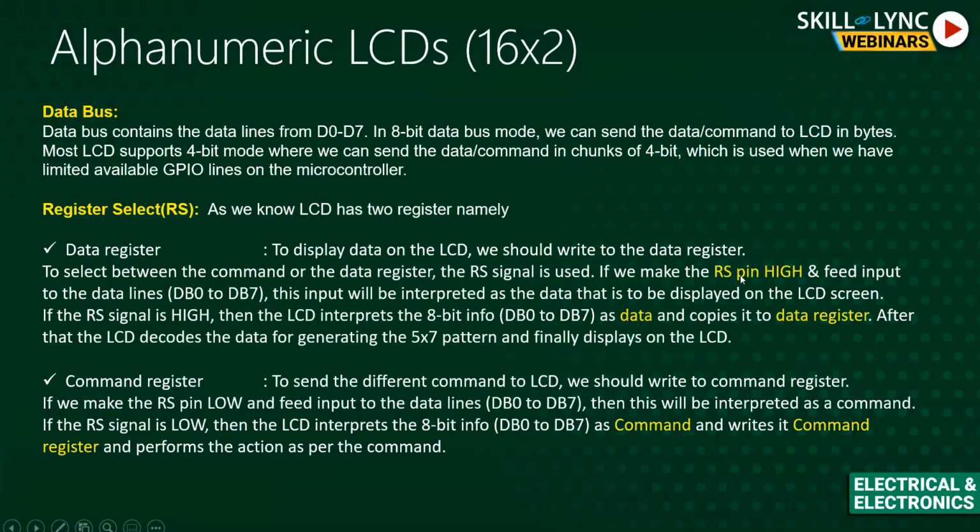Now after configuring the RS pin to high, whatever value I load on the data bus DB0 to DB7 will be interpreted as data, because I am instructing the LCD that whatever comes now should be interpreted as data, not as a command.